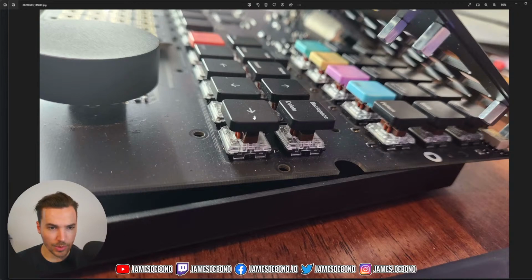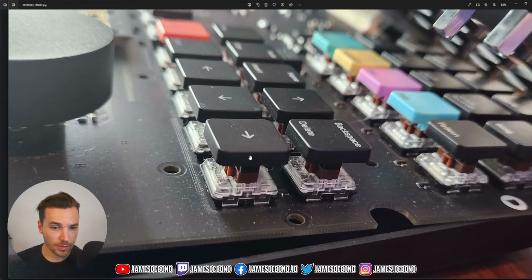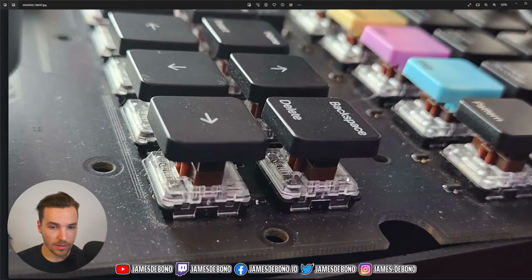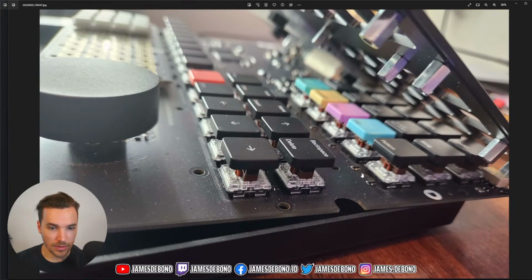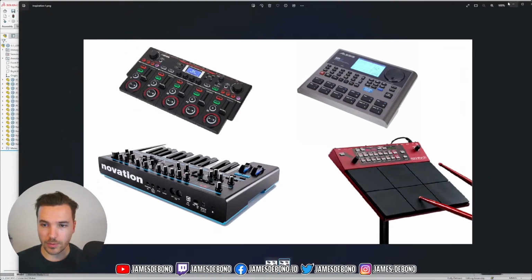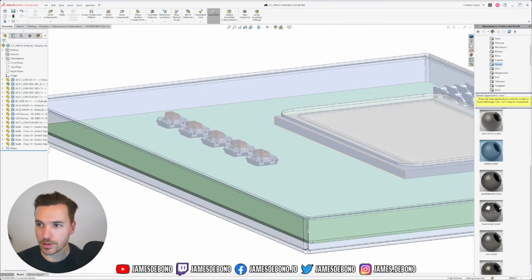So probably I'm going to have to do the same thing. I wouldn't be able to use their keycaps because I would have to have the exact same height of the PCB from the top plate, and I don't know what theirs is, and it might not be right for mine, so I think probably we need to do custom keycaps.